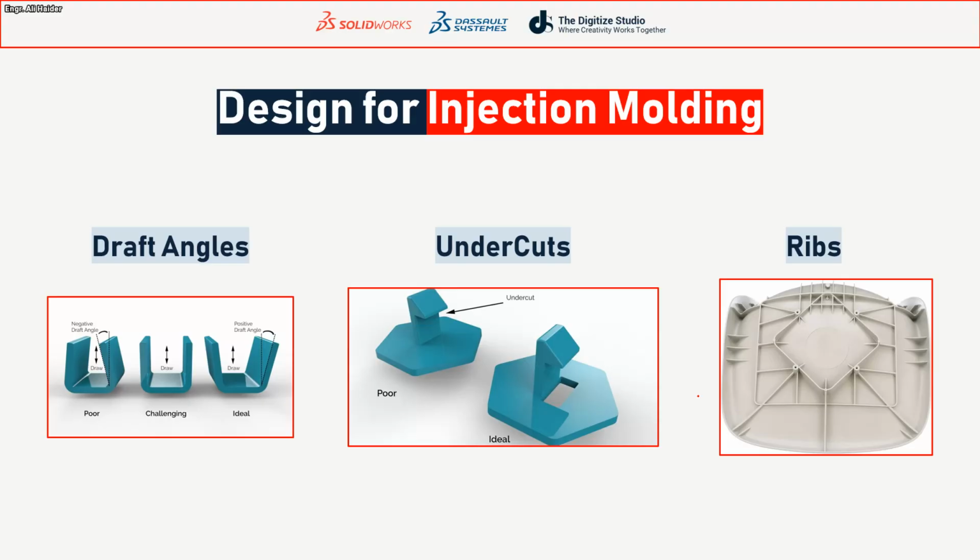So that's why you have to avoid that thing in order to clear the draft angles as well. So first of all, here we have our part that has no drafts, right? If I want to manufacture this, we will have a core on the top and the cavity on the bottom. This part will go upward and the bottom part will go downwards.